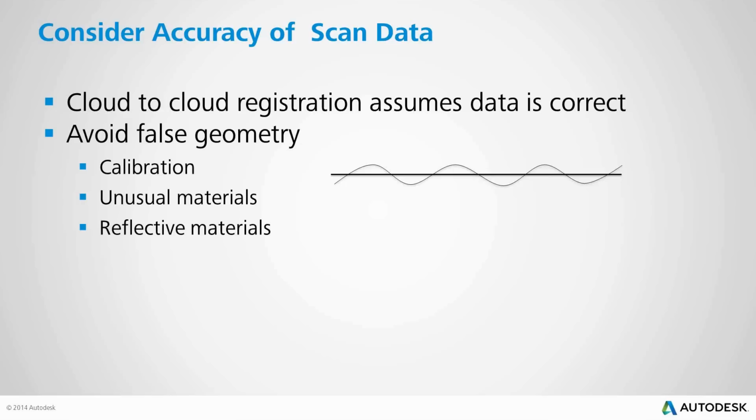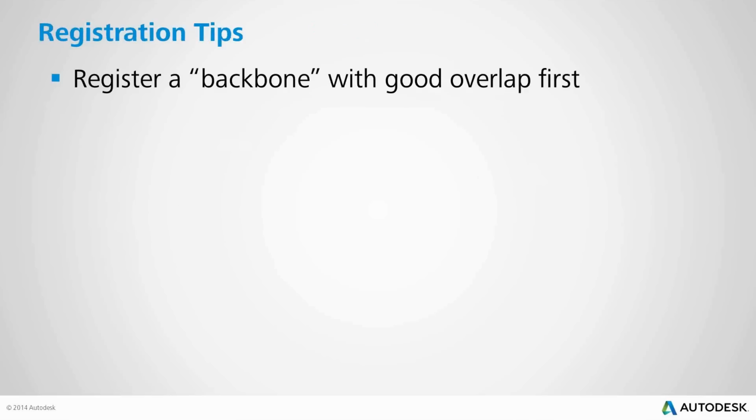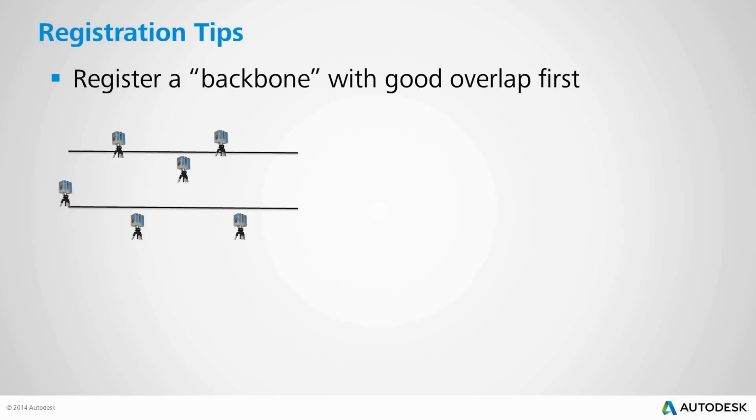Pay attention for that. Some other things to think about in terms of the registration process itself. Let's say that you're scanning in an office building where you're hopping around through the hallways into office rooms and back and forth. You don't necessarily need to register in the order that you're collecting this data. You can actually go about it in a different way.